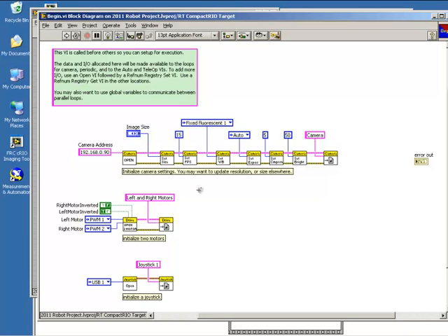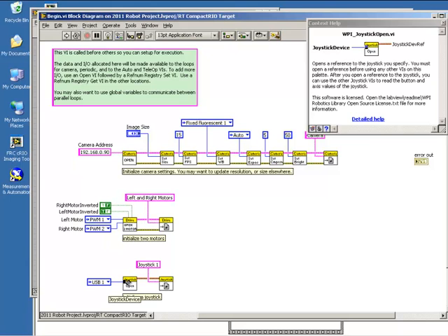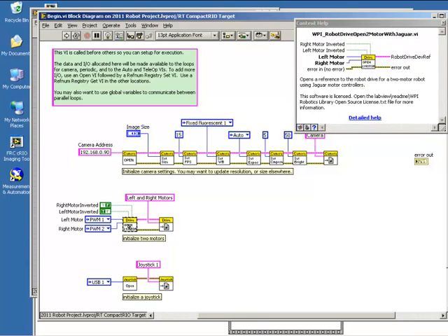This sub-VI is used to initialize all the hardware used by the robot. This program already initializes the camera, the 2 drive motors, and the joystick on the remote controller. Press Ctrl-H to open the Context Help menu and mouse over the icon that says Drive Open to Motor. This function allows you to select which PWM outputs on your digital sidecar are physically connected to your drive motors.